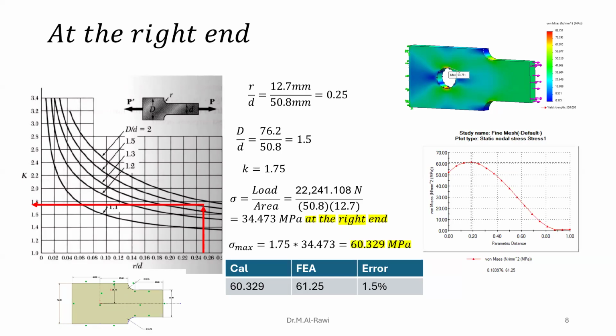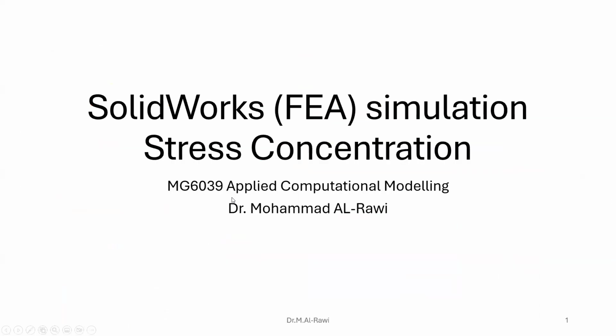You say, hey, my shape you give me, or any shape you give, when you design it in CAD, you use evaluate, get a section, highlight that section, and it will give you nicely the area you're interested in. And you use the area, instead of multiplying as I did here, you just use the value from the CAD. And then the stress, the load you're applying for it. So if you're weighting scales, you measure that. And that could be for any geometry. So that is the question we just worked on last week.